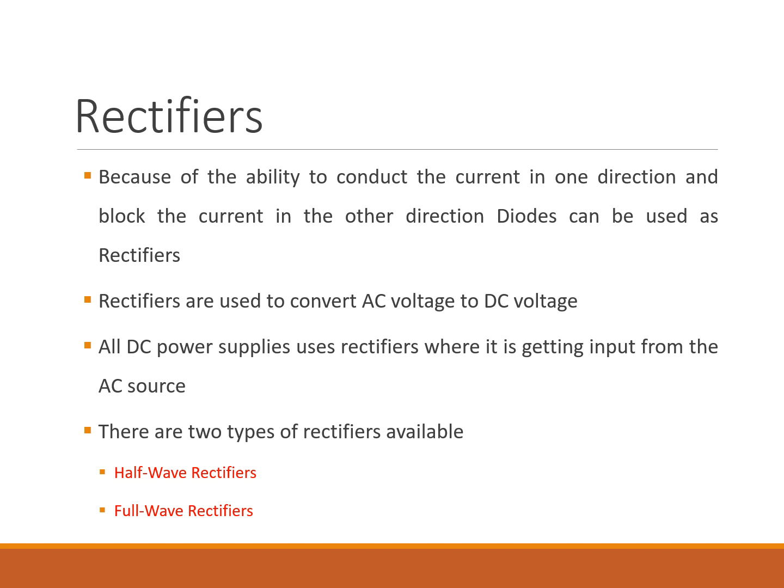So a full wave rectifier lets both of the halves of the AC signal actually go through. It does it by flipping the negative half. Again, because you're utilizing both the positive and negative cycle, this ends up being more efficient. You'll have smoother power output. And a key point is that a diode's ability to block reverse current is what makes all of this possible. So no diode means no rectifier. No rectifier means no DC.